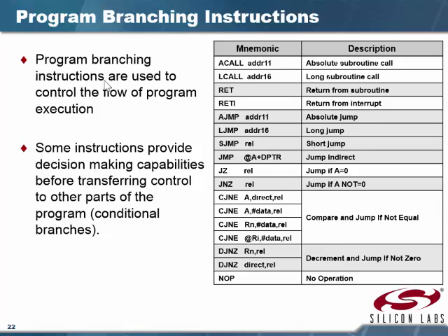The first four here deal with function calls. Actually, this one is a return from interrupt. So anytime you write an interrupt service routine, and we'll be looking at one in probably about two or three weeks, we'll be writing a short little interrupt service routine. Whenever we're done servicing the interrupt, we want to put a return from interrupt, because that tells the microprocessor that we want to pop the return address back from the stack.